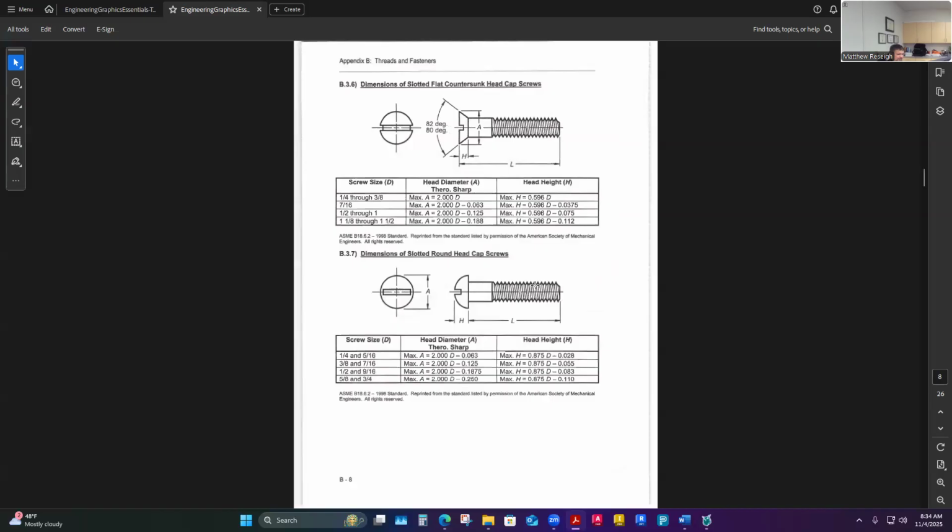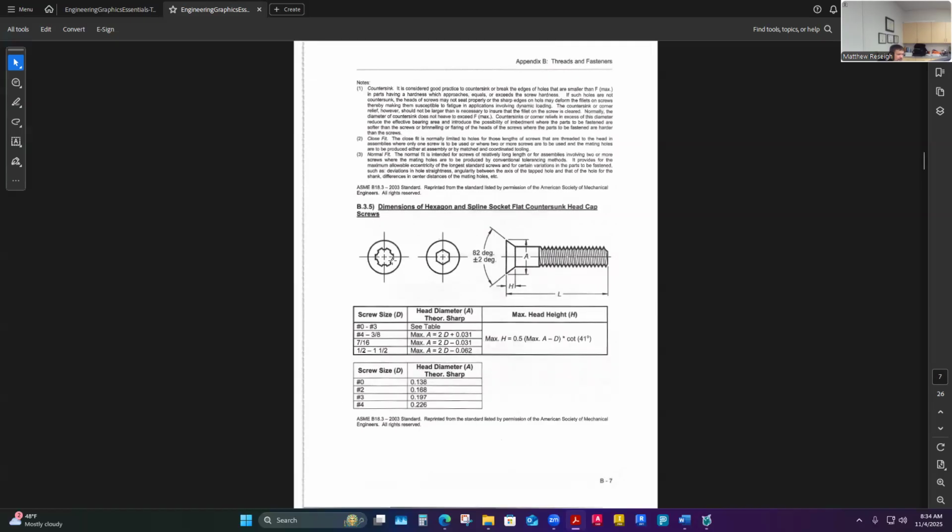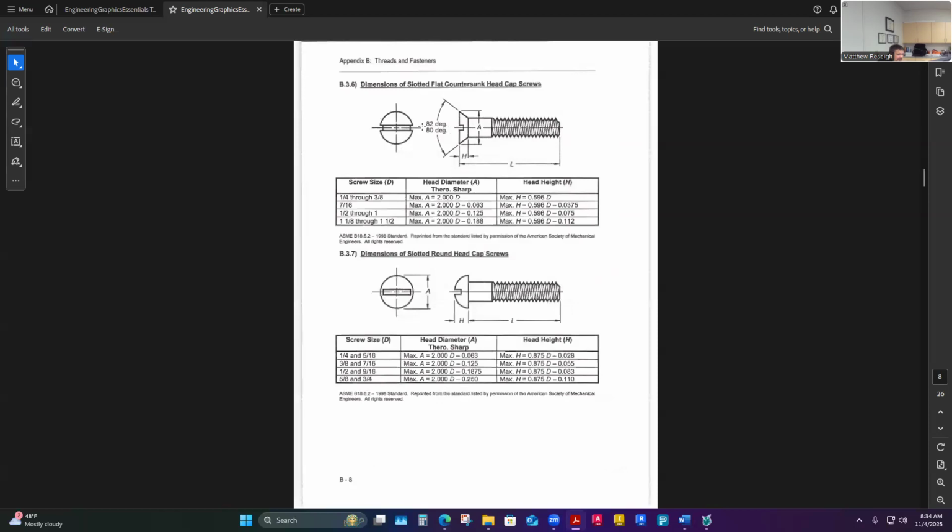Okay, then we've got some older ones, I view these as kind of old-timey. Yeah, here's a flathead machine screw with a slotted head. Oh yeah, this is much more common these days, I think. They definitely still manufacture these. Like I said, they're just hard to torque down with the amount of contact from the bit to the head, unless you've got the right bit exactly sized right, which we never do. We never grab the right tool for the job generally. That's why our fastener heads get stripped and worn and wobbled and then you can't fit the bit in them anymore. Yeah, that happens a lot because we're using the wrong tool, wrong size.